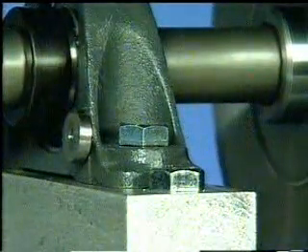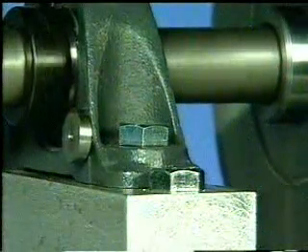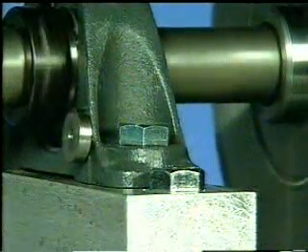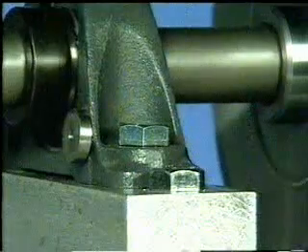When performing phase analysis on a machine, remember that looseness can exhibit a directional phase of 180 degrees between components and erratic phase indicating rotating element looseness.